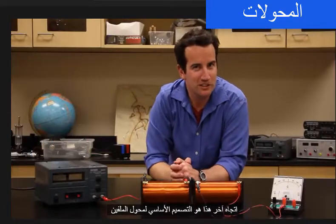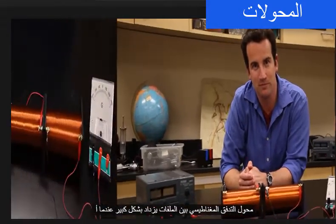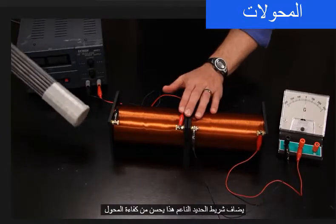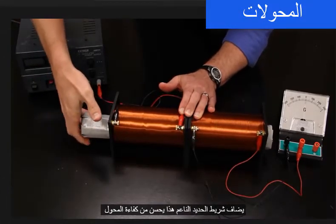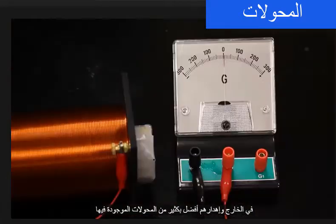This is the fundamental design of a transformer. Two coils that are connected magnetically but electrically separated constitute a transformer. The magnetic flux between the coils is greatly increased when a soft iron bar is added. This improves the efficiency of the transformer by strengthening the field and preventing it from diverging out and being wasted. Whoa, much better.